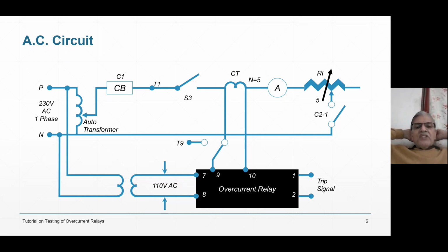And one switch S3, single pole switch S3, 15 ampere switch is enough. 15 amperes. Terminals of 20 ampere are also enough, right? Rheostat, the value I have written somewhere. We will see the value of the rheostat. 5 ohms rheostat is there, right? Then C1 and C2 are the contactors. And what their contacts are doing, that we will be seeing.